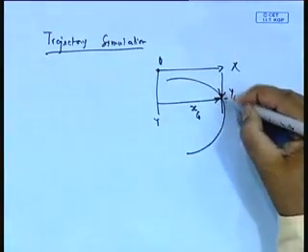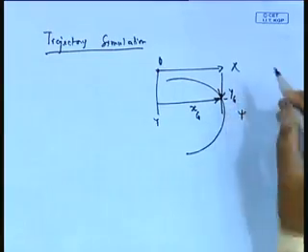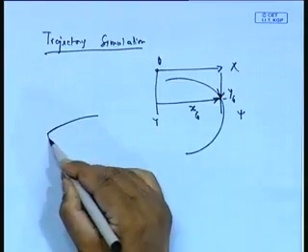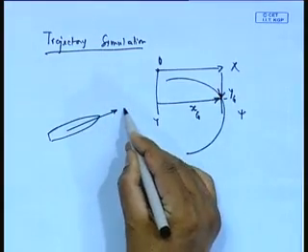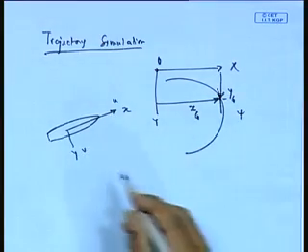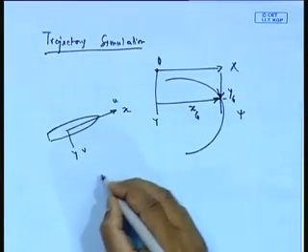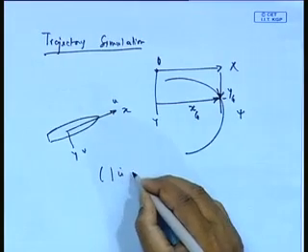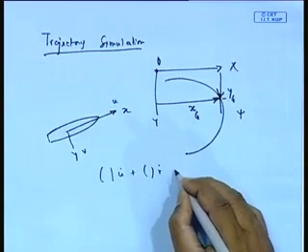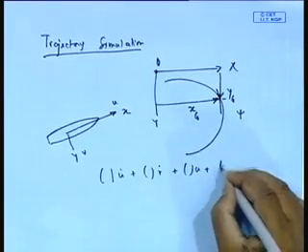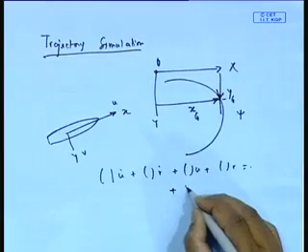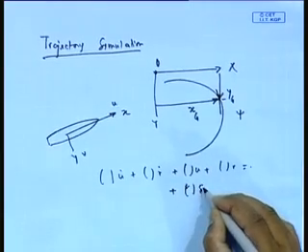Now, I have written the equation of motion with respect to the body system, remember. According to the body system, I have x, y, u, v. If you remember, I have an equation where something into u dot plus something into r dot plus something into u plus something into r, etc., plus something into delta, that is rudder angle, equals 0.